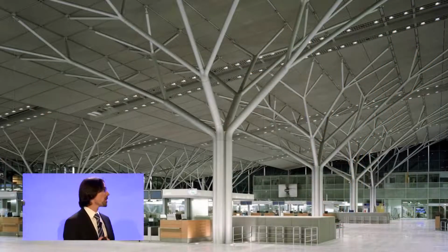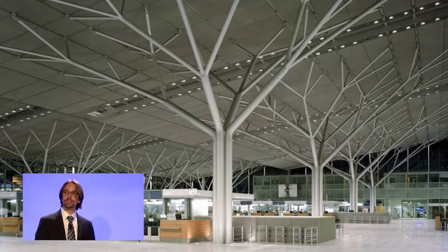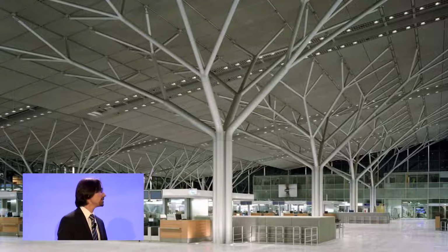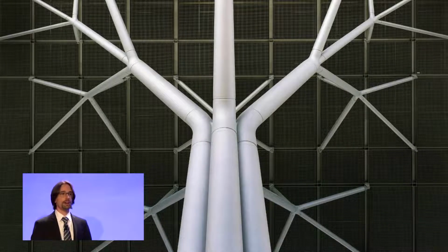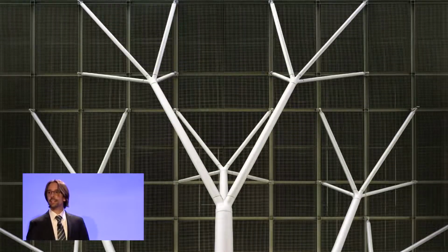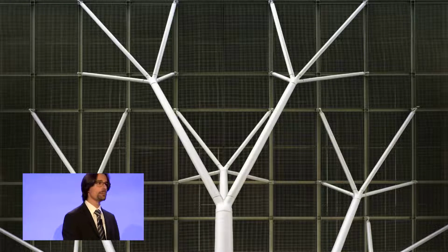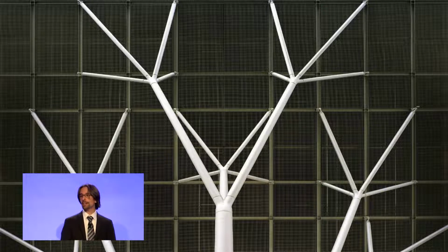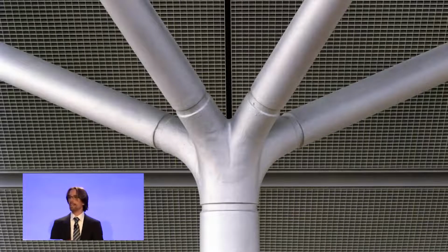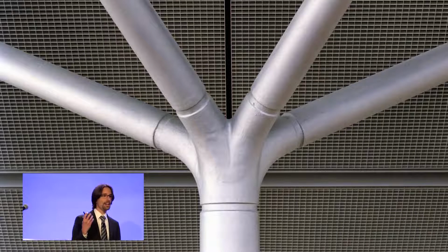So it didn't take long for architects to realize this and to start incorporating steel castings into their architecturally exposed structural steel. So here you see tree-like structures that are comprised of hollow structural steel sections and cast steel nodes. And those nodes at the intersection points where all of those structural members come together, they're obviously geometrically complex, highly loaded, they would be difficult to fabricate otherwise, but you can appreciate that that cast steel node is really selling the architecture or the design of that tree.